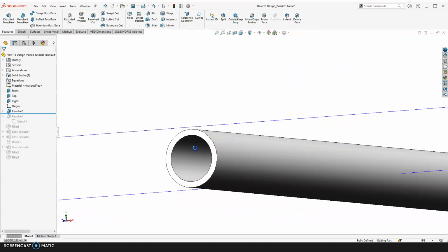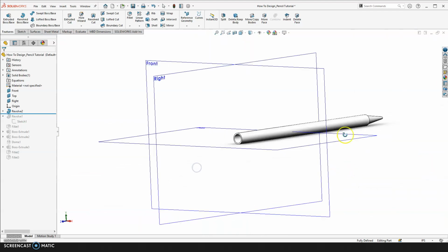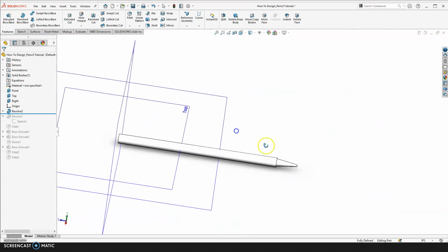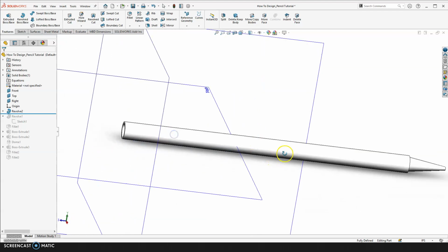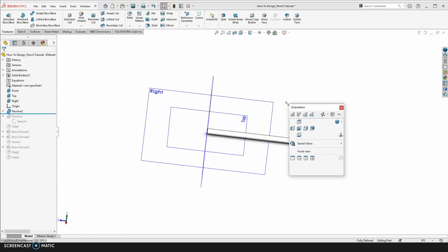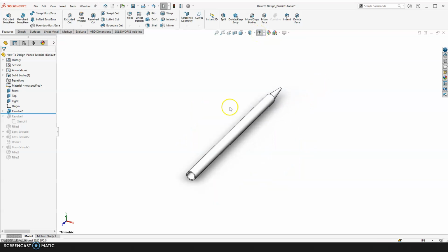And if you look at it inside, you have a hollow feature here, right? Okay. So what I can do is I can start putting colors to these lines. But here I'm going to turn off the datum planes. Just go to hide all types, and you can hide the planes here.